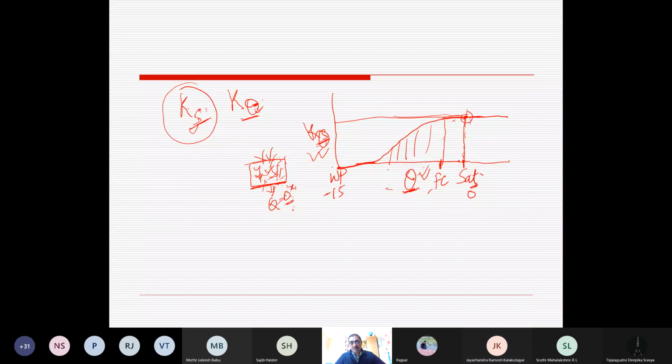Yes. Anybody? Okay. Now you have learned that water is either raining on the soil surface or supplied through irrigation. Water is spread over this surface and starts entering into the soil, that is infiltration. Then it moves inside the soil, and once it is saturated, theoretically all pores are filled with water, and then water moves below this level to the root zone depth, where we have our interest.